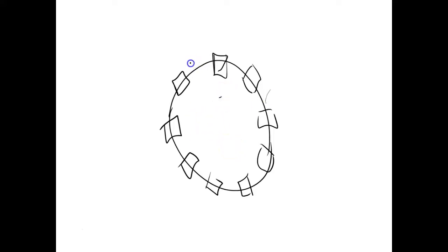Well, what we're dealing with is this guy right here. How do we connect these networks together? This is where the impedance matching comes into play. So I can't just hook up any cable I want to, right? You understand? I have to hook up the right impedance. It's just like I was talking about. I couldn't go out and buy an RG58 cable, even though it looks the same, and hook it up to my TV.